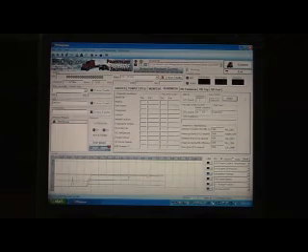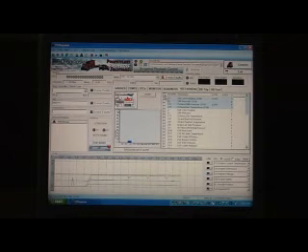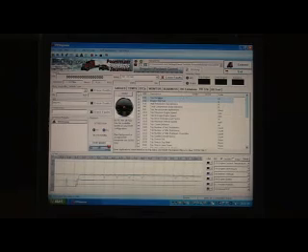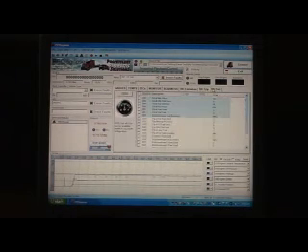Readiness is for OBD2 purposes. HD emissions, again, the same rule applies. Check the box. Wait about 30 seconds for the information to populate, then uncheck the box. That will ensure that you're getting the maximum available PIDs displayed. HD trip: check the box, wait 30 seconds, uncheck the box. And HD fuel, the same thing once again. Check the box, wait 30 seconds, uncheck the box, and that will ensure you're getting the maximum amount of information that PF-Diagnose can request from this engine.